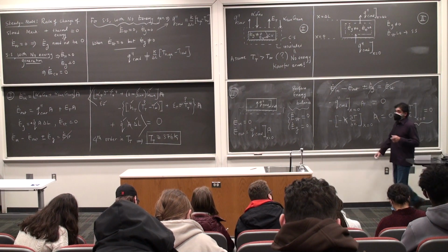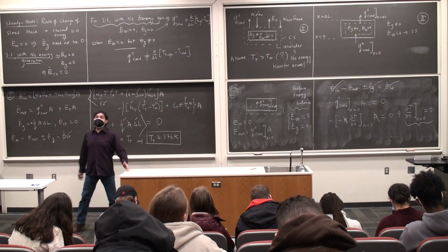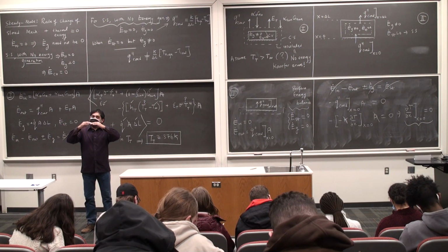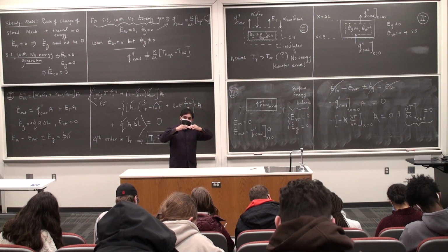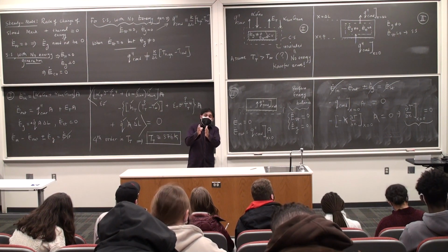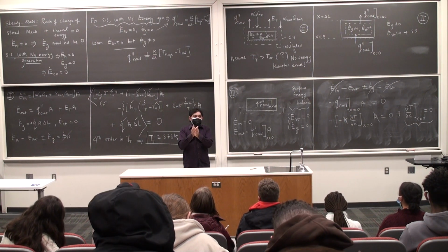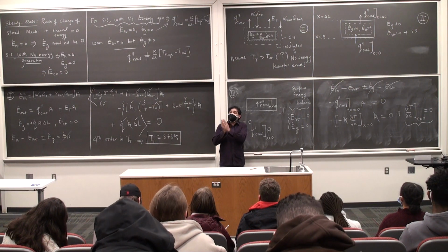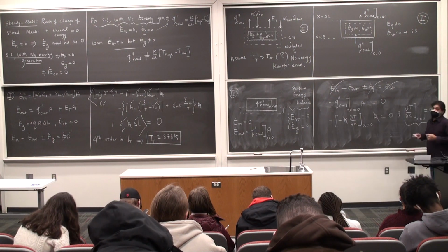And so what I'm getting is an important thing, which is why I want to talk about it. This is called an adiabatic boundary condition. It's a boundary condition. This is not throughout the body. This is at the boundary, x is equal to 0. The variation of the temperature as a function of x is 0, which does not mean the temperature is 0 at that surface. That cannot be the case. This tells me that the rate of variation of the temperature with respect to a spatial quantity is 0 at that particular surface. So this is called an adiabatic boundary condition.